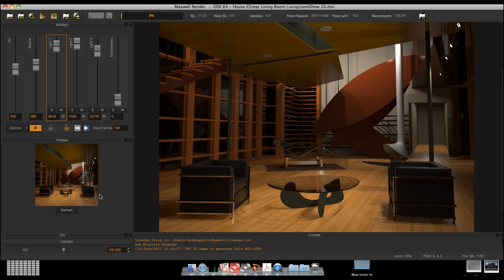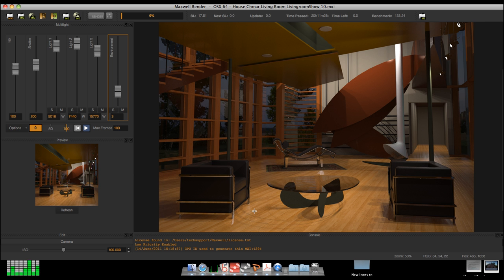And it turns out that this is pretty much infinite. Let's say looking at this glass material over here. Now that it's dark outside, I see the reflections of my objects in that glass. And of course, that's important for realism. What if I want to have some sensation of the sky and trees out there? Well, all I need to do is up the environment knob a little bit here and then click the refresh button again, and so that'll update. So now I'm actually getting like a late evening type image.